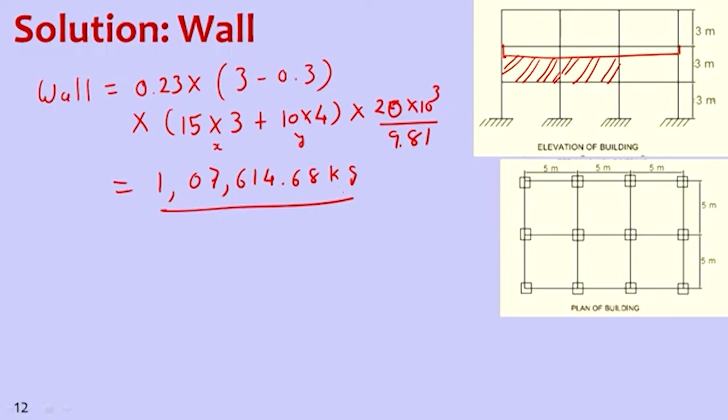These walls are interior and exterior. Now if we calculate the parapet wall mass, it is 0.3 thickness. On the rooftop we don't have anything, so the height of wall will be 1 meter, into length. As we know, the parapet wall is provided for protection, which will be at the periphery.